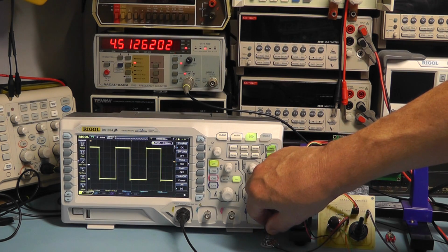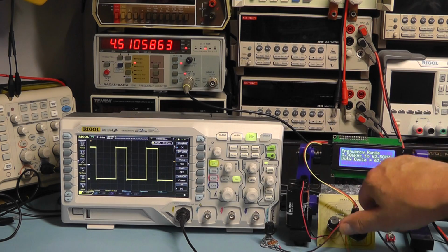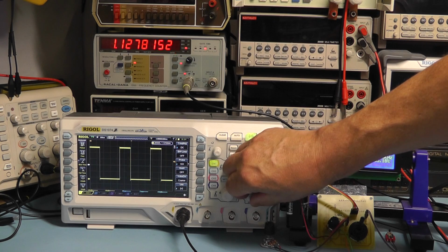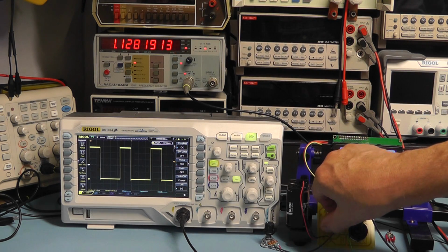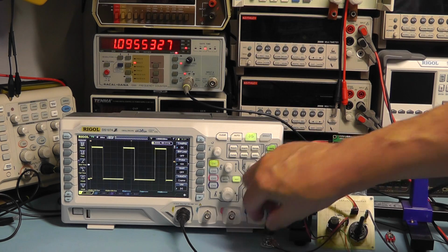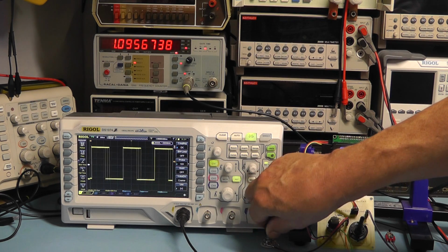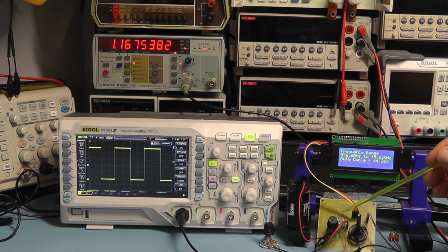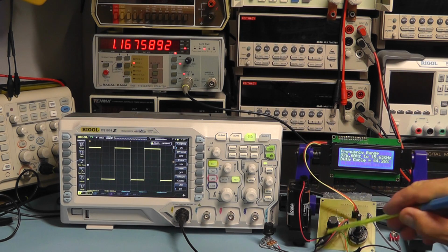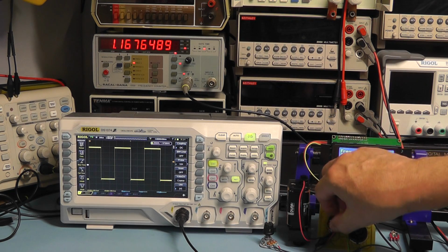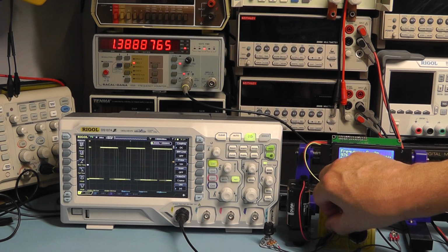We don't get that problem at the lower frequencies, but we do get it at the higher frequencies. Again, we can still change the mark space ratio. So let me just go back down again to the lower frequencies, and on the lower frequencies it's much more stable, and again altering the mark space ratio. What I've found now is that if I earth the casing of the frequency potentiometers, I've just clipped a little crocodile clip on there and then taken that flying lead down to ground, and I'm finding that it's more stable as I alter the control now.